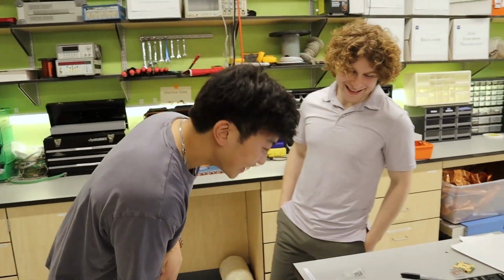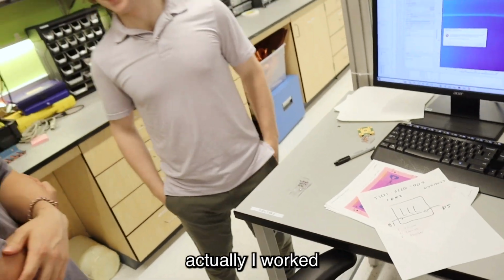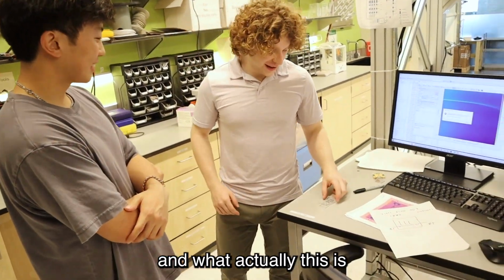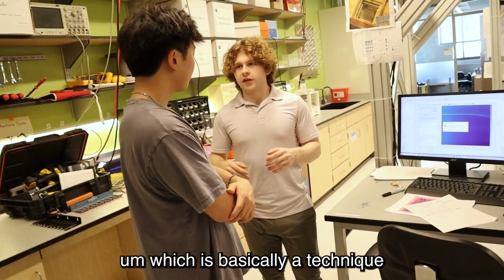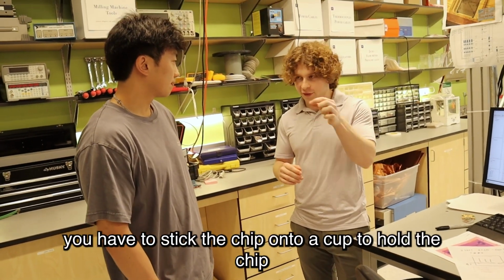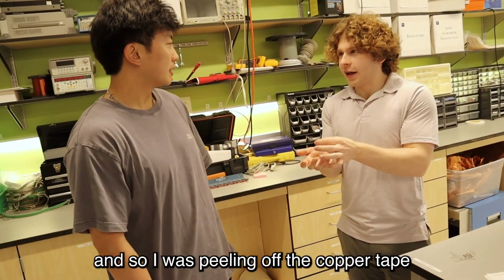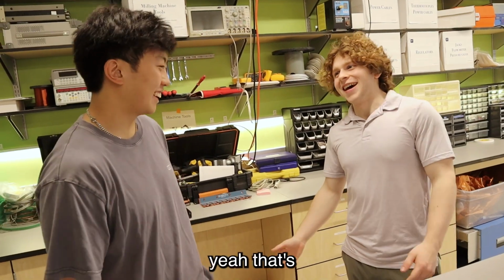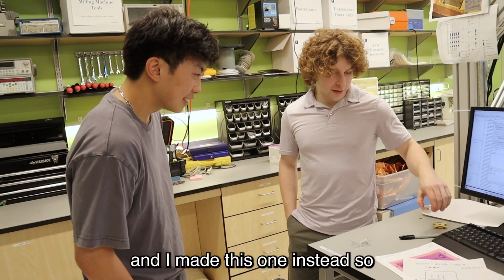Inspirational. That's great. So how did this one break? This one broke. It was really sad, actually. I worked for a few hours sputtering aluminum on it. And it's a really dumb thing, but when you're sputtering, which is a technique similar to molecular beam epitaxy, you have to stick the chip onto a cup to hold the chip using copper tape. I was peeling off the copper tape, and the chip just broke because I peeled off the tape too hard. Oh man. Yeah, that's life. That happens sometimes. But it all worked out, and I made this one instead.